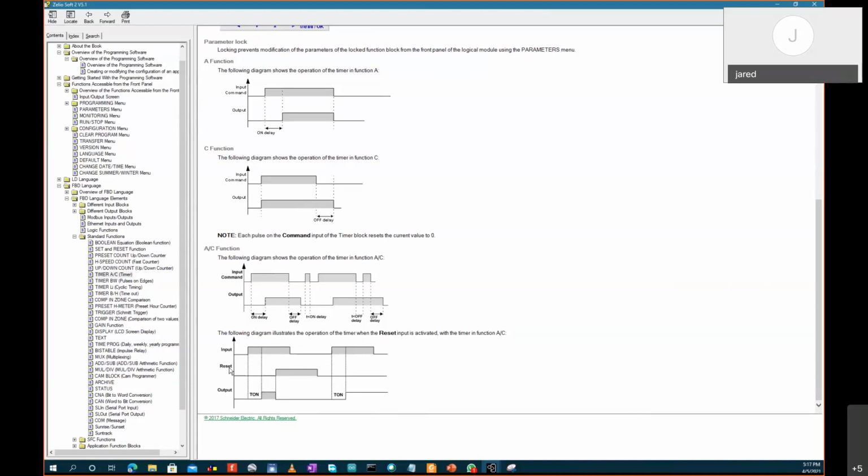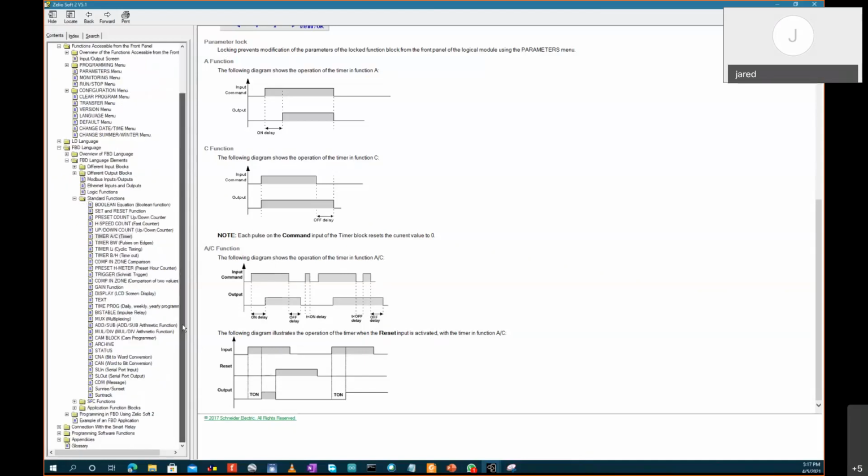If you reset, if your reset button is high, that means it transitions from 0 to 1. The whole output goes to 0. What does this tell you? That reset in most cases takes precedence over enable, because it's like an emergency stop.